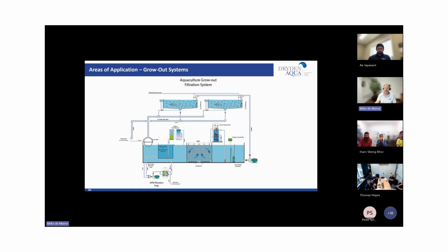So this is, again, a concept that, coming from our experience both in aquariums and aquaculture, we would say this concept would work very well using the AFM filtration media, because the last thing you want to do is have any organic load in your denitrification system. It just compromises the denitrification system and creates problems for pH and the possible release of H2S into your system. Okay, and again, whether you use oxygen concentrators by nanobubbles or Venturi systems or Spice cones or whatever it is, those will always be required, right? Okay.